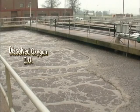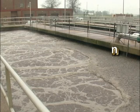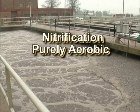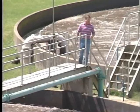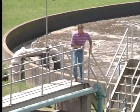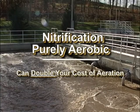Factor number 2, dissolved oxygen. Nitrification is a purely aerobic process that requires a large amount of oxygen. In fact, it requires 4.6 pounds of oxygen to oxidize 1 pound of ammonia into nitrate. Comparatively, it takes approximately 1.1 pounds of oxygen to oxidize a pound of BOD. The requirement to nitrify can almost double your oxygen requirements and aeration costs.